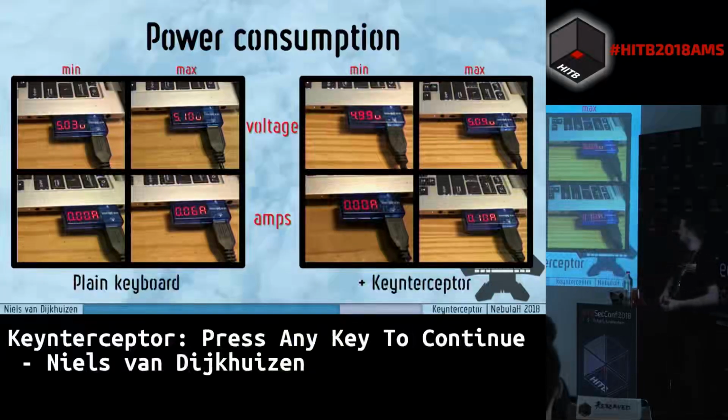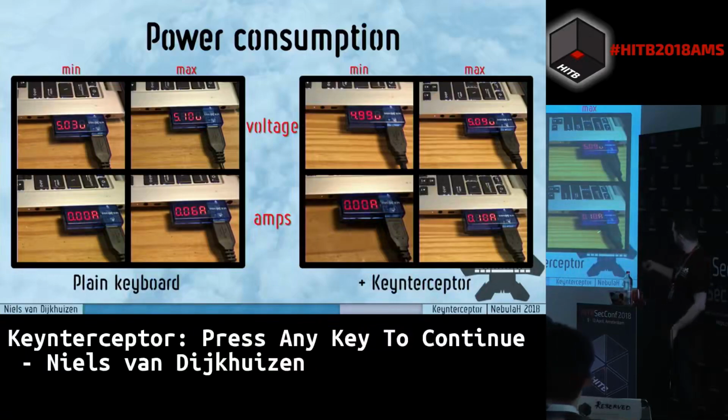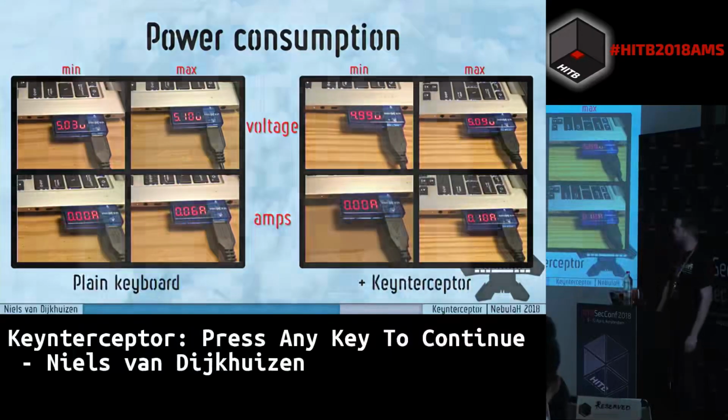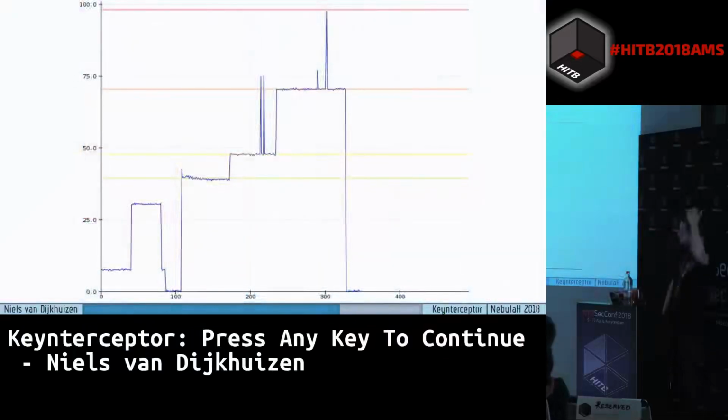So when I started, I thought, let's measure power, because we cannot go beyond the limitations. Normally for a keyboard, it would be 100 milliamps max, if you look at the specifications. So I stay under the radar. It's 100 milliamps max, but this device is crap. It's not very accurate, so I did some remeasuring. This gives us better insight into how the power consumption is actually doing.